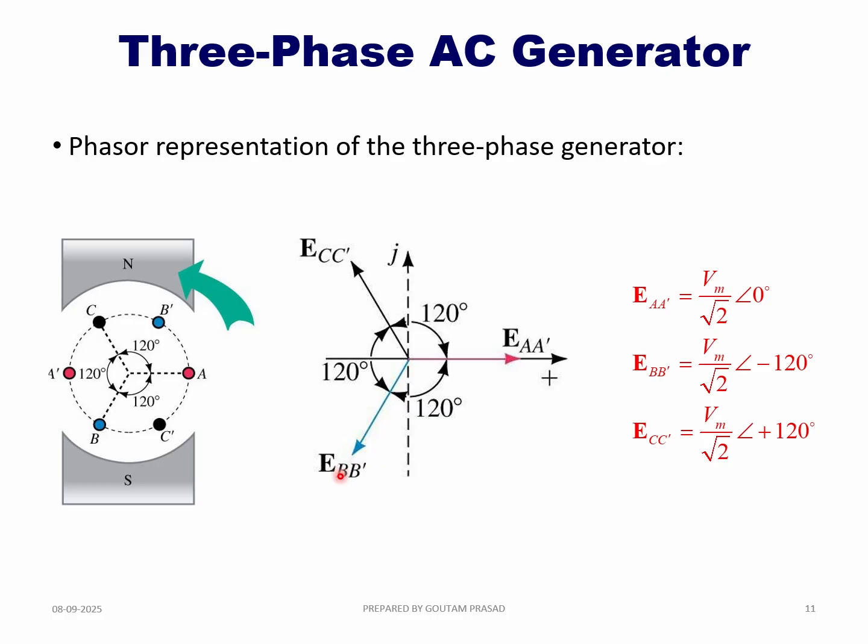Here the phasors have been shown. These phasors are shown here in a static manner. They are not rotating here, but in fact they are rotating phasors. They keep rotating in the anti-clockwise direction, which is the direction of rotation of the rotor, as shown here. So this is the R phasor, this is the Y phasor, and this is the B phasor. These three phasors are rotating, but for simplicity of understanding, they have been shown static here.